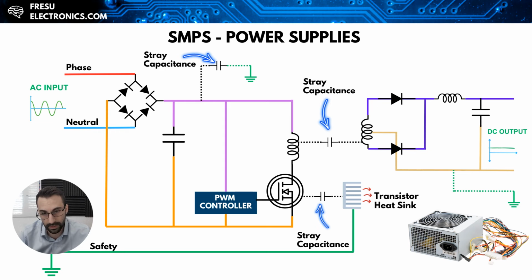As discussed in other lessons and also in some of my other articles, there are 3 possibilities to solve EMC issues, and these possibilities are related to either the source, the path, and or the victim of EMI. So we can reduce the source of emissions, for example, by taking action on the switching transistor and either changing the switching frequency or slowing its switching times. Unfortunately, this can result in lower performance and also increase the losses, as we directly impact the switching wave. And changing the frequency will only shift the level of emission to other frequency ranges, which may not really solve the issue.